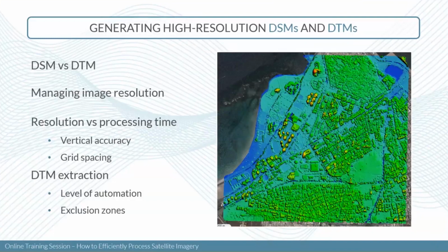So if you're working with maybe 30 centimeter imagery, you can go with a one-to-one matching, but you're going to have much more noise than expected in the output. So usually getting something around 1 meter is a good compromise between speed and accuracy of the processing.